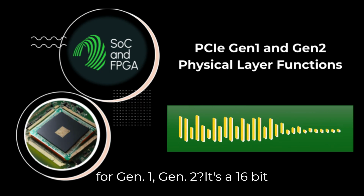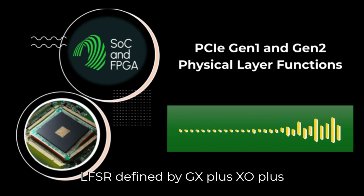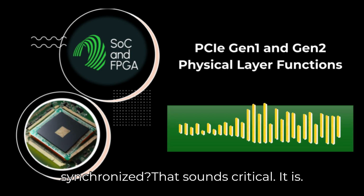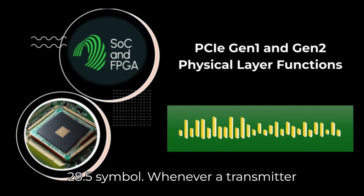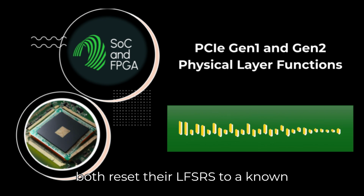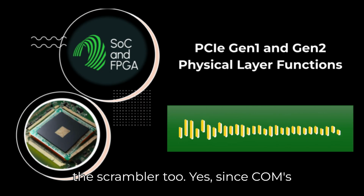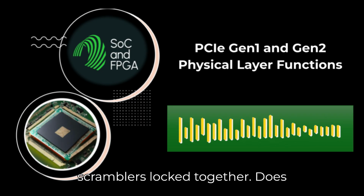What's the polynomial for Gen 1, Gen 2? It's a 16-bit LFSR defined by G(X) = X^16 + X^5 + X^4 + X^3 + 1. That specific formula dictates how the sequence is generated. And how do they stay synchronized? That sounds critical. It is. Synchronization happens using the COM, K28.5 symbol. Whenever a transmitter sends a COM or a receiver sees one, they both reset their LFSRs to a known starting state, all ones, FFFF hex. So COM acts as a resync point for the scrambler too. Yes. Since COMs appear frequently, especially at the start of ordered sets, it keeps the scramblers locked together.